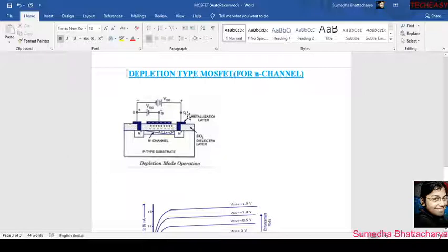But we know in case of JFET that there is also a counter effect of increasing VDD. What? It creates a reverse bias. For reverse biasing, the depletion region will increase and the current will saturate at one point, the same case as for JFET, right? Now how is the depletion region created? You can see here this is the drain terminal with positive potential and here is the N channel. So the N channel is connected with positive potential and the P type substrate is with negative potential. So here the reverse biasing will be more and more, so the depletion region will also be more and more. The increase of the depletion region decreases the amount of current flowing from drain to source, and one time will come, that is the pinch off voltage.